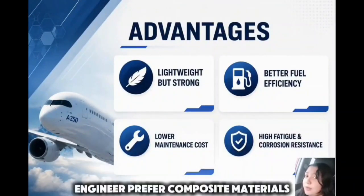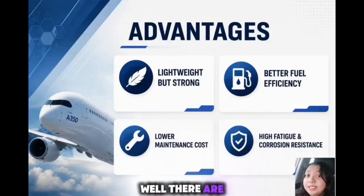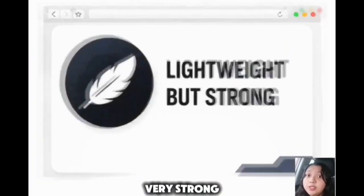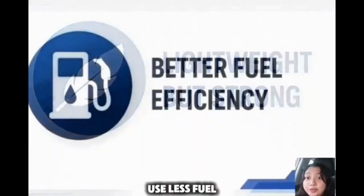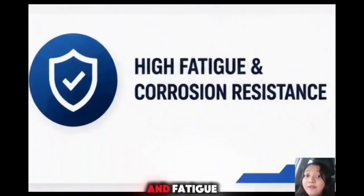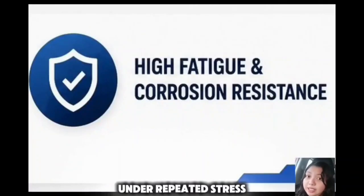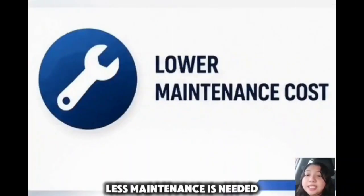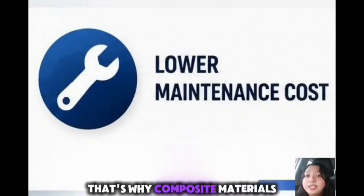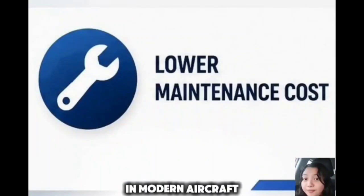So, why do engineers prefer composite materials? Well, there are several advantages. First, they are lightweight but still very strong, so the aircraft becomes lighter and uses less fuel. Another advantage is that they resist corrosion and fatigue, which means they can last longer under repeated stress. Because of this, less maintenance is needed and operating costs can also be reduced. That's why composite materials are widely used in modern aircraft.